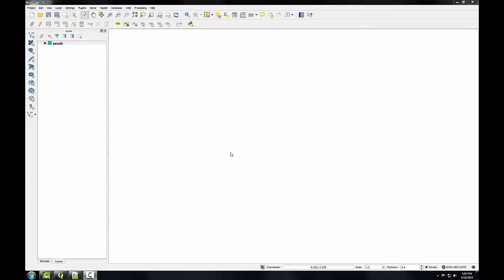Now that I've created an empty shapefile to store the digitized information, I'll perform a coordinate transformation, also known as georeferencing, on the source dataset to put it into an Earth-based coordinate system. So in this case, we're taking it from coordinates that a scanner provided, and we're going to put it into the same CRS that our parcel shapefile is in, New Mexico State Plane Central.